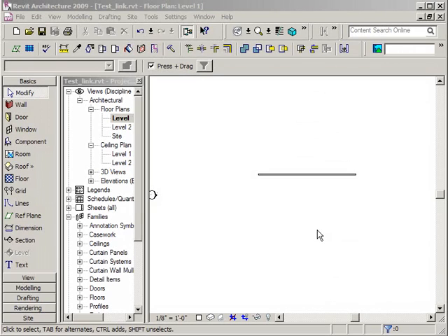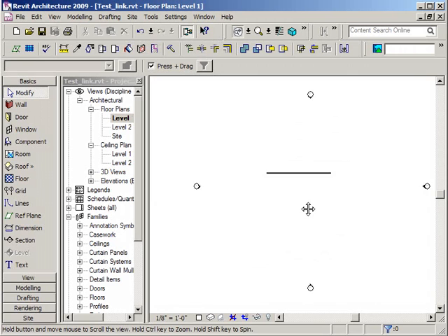Okay, for this video tutorial we'll be discussing how to create a plan region. They're not too difficult to deal with, but one reason you would want to create a plan region is if you have a clerestory window, for example, that sits above the view range normally set up, or the current view range you've got set up for this specific view.